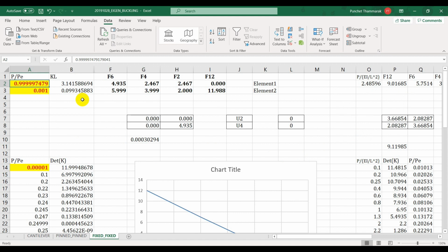So the buckling load over here in this definition is equal to 4 times pi square EI over L square, as your effective length reduced to 0.5 L. Right? Buckling load increased to 4 times. So your PO/PE at the buckling of this system is equal to 1, and then multiply by 4 pi square EI over L square, which fits with what we used to derive. Right?